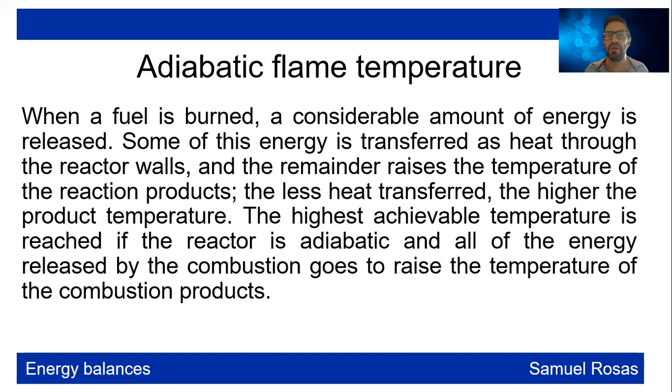And one concept that we're also going to be working with is the adiabatic flame temperature. This is a temperature that occurs in the reactor when the fuel is burned and a considerable amount of energy is released. That's the reason why we are actually burning fuels, to release heat, and this heat is going to be used to produce some work. Some of this energy is transferred as heat through the reactor walls, and the remainder raises the temperature of the reaction products.